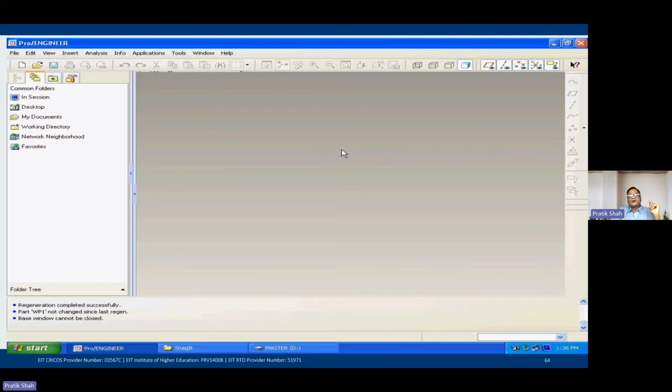Now I need to go for the second step, that is the machine settings. I need to define the program 0 and the machine 0. Many of you might be aware of this. What exactly is program and machine 0? The program 0 is basically the point from where the reference is taken, because I need to create a tool path which will exactly machine the additional material, subtract it and form the job.